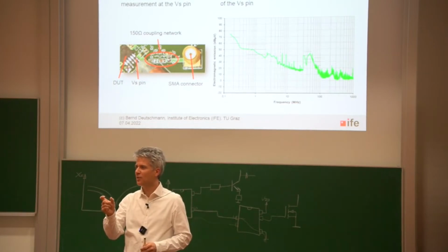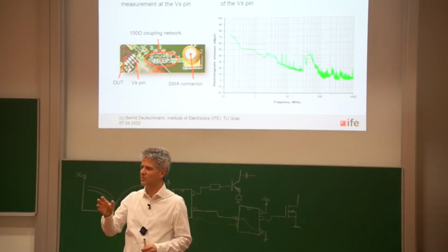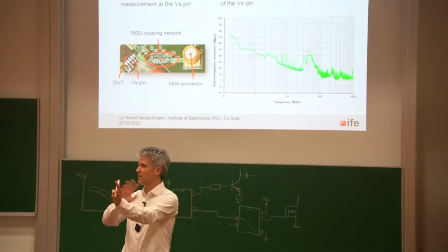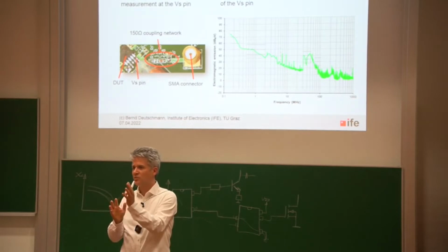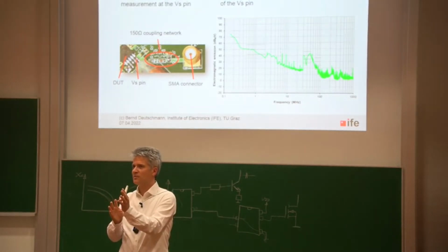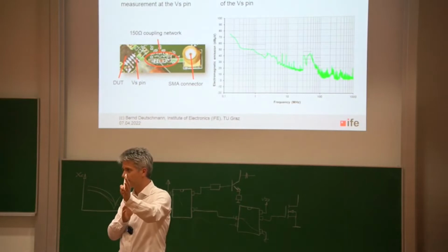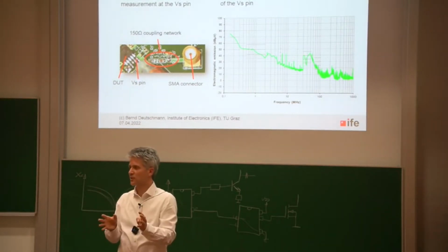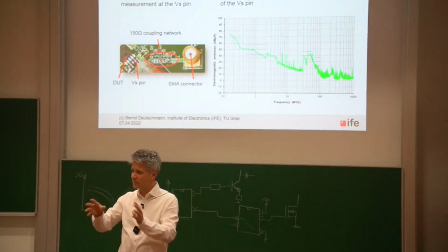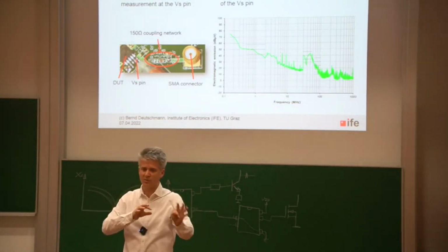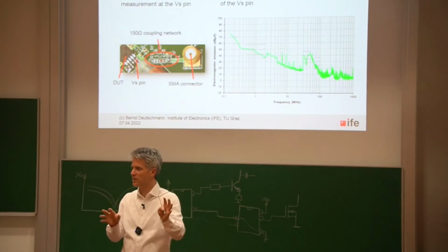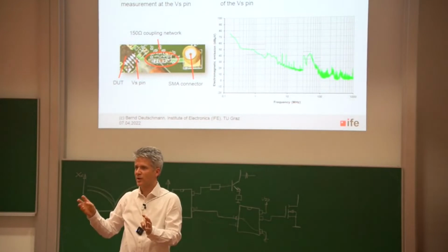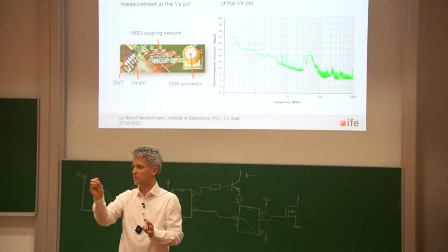So usually all the electromagnetic emissions that are generated by the switching activities of the ICs, not just one switching activity, there can be many different switching activities, are during this time frame sometimes in phase. So for example, I have 5 different sources of the electromagnetic emission, and a certain resonance that is built by a capacitor in combination with a parasitic inductance in the package can cause a resonance effect where I have increased electromagnetic emission in a certain range.